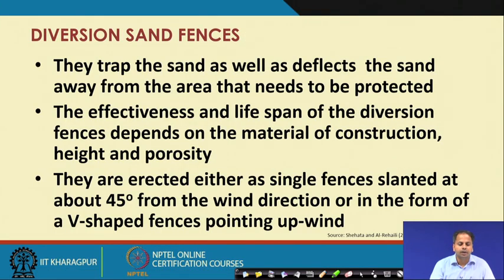Then let us see the diversion sand fence. The idea here is to divert or deflect the sand movement, or deflect the wind. They trap the sand, and the purpose of these diversion sand fences is that they trap the sand as well as deflect it away from the area that needs to be protected.